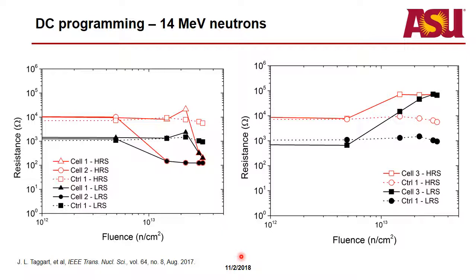For the prior test, since I was gradually stepping up the fluence, I only did 1 IV sweep, so that if we did see changes, we knew that it was due to radiation and not to wear out of the device, because doing the IV sweeps puts a lot of energy into these devices and can cause material damage over time due to joule heating. So to limit that, we try to limit the number of IV sweeps we do.